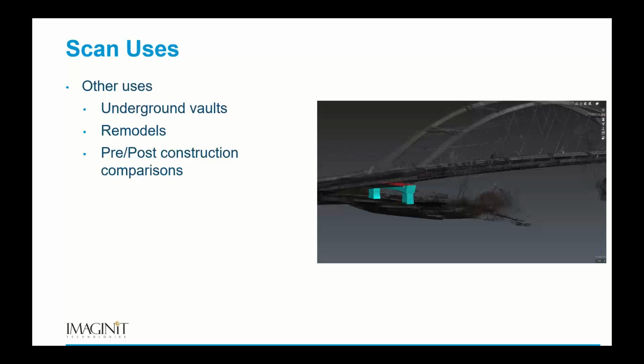So I would like to see a lot more of that. It's becoming popular. The other thing is, if we laser scan it, I'm able to see where all that rebar is at. So I scan it before the pour. We make sure everything's right. I scan it after the pour. I combine those two. Wow, that's called an as-built, a very accurate as-built. So now I see the floor, all of the rebar, all of the floor penetrations, and then I can overlay that Revit model or that AutoCAD drawing and make sure everything lines up, but I'm also collecting that data for an as-built condition.